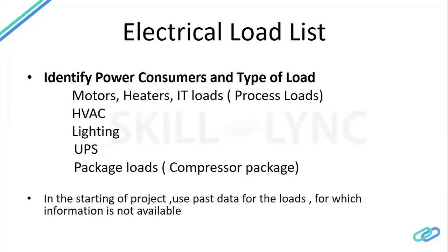So your first responsibility is to get all the equipment which needs power in your project, like motors, heaters, and IT loads. I'm calling it a process load, because process is the industry you are working in. If you are doing a project for a building, then HVAC and lighting are the main loads. If you are doing it in some manufacturing plant, then motors and heaters are the main loads. They call them process loads.